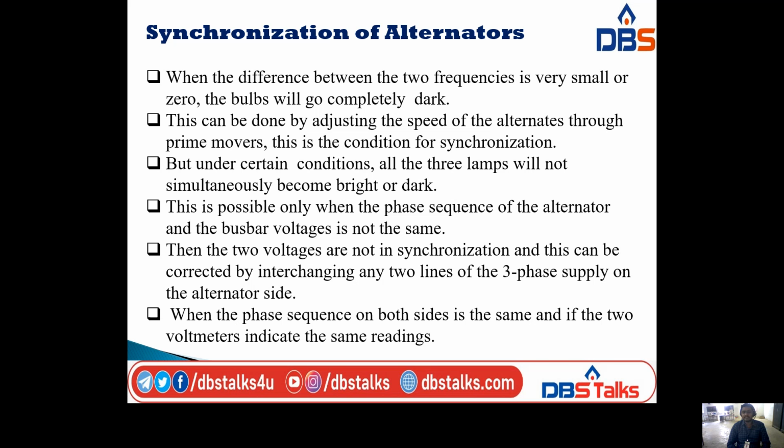But under certain conditions, all the three lamps will not simultaneously become bright or dark. This is possible only when the phase sequence of the alternator and the busbar voltages is not the same.